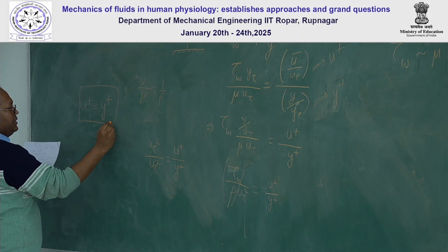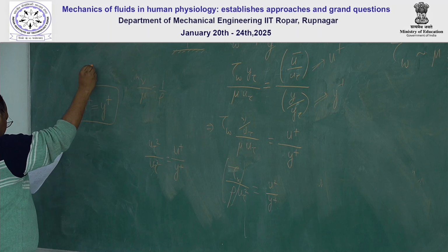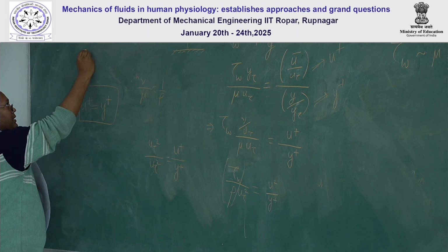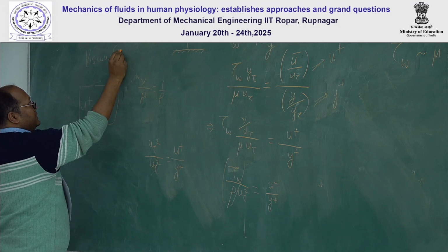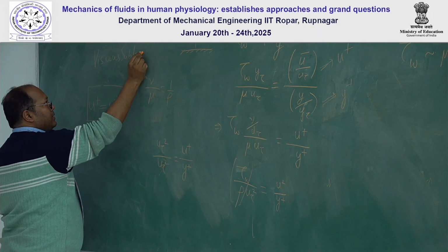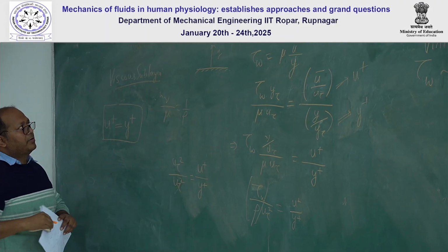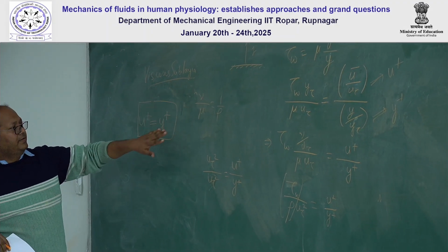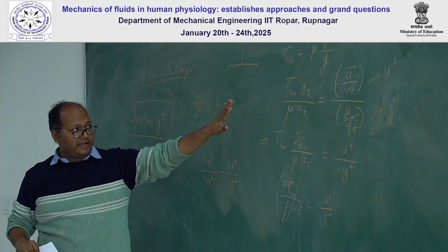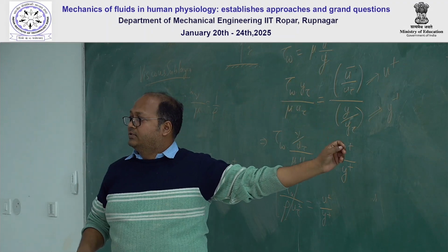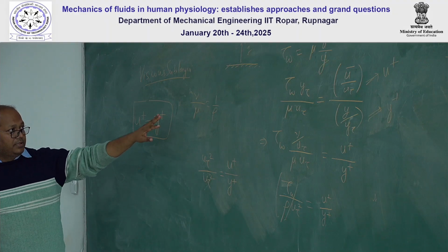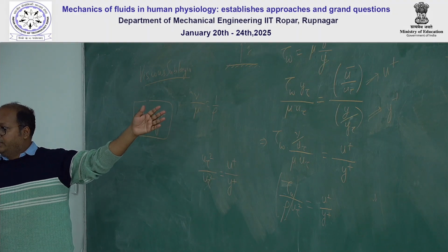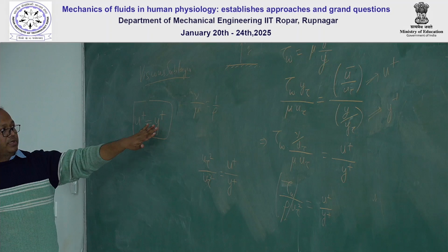And this is called the viscous sublayer. This name is given because we are essentially stressing the fact that there is hardly any Reynolds stress, only whatever term is coming out is happening due to the mean velocity gradient. So that's why u plus equals y plus.